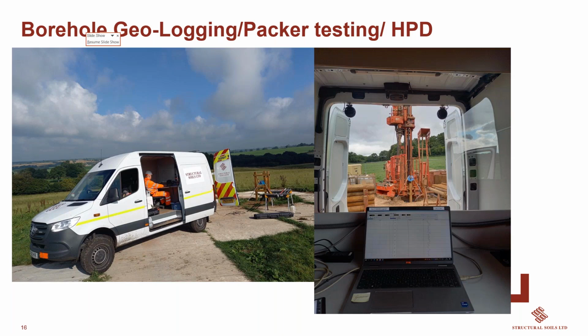So once we've drilled our borehole, we need to make sure we get as much information out of it as possible. So what we'd like to do is run some geologging tools down there. This can be done with the rig being in situ, or if the rig needs to move on and go to another borehole and carry on drilling, we can run it with a tripod and run the tools up and down the borehole without the rig. So we're minimizing the downtime of the rig. However, sometimes with packer testing and with HBD testing, unfortunately, the rig does need to be in situ. So again, we need to basically keep a handle on the program on that so that we understand how things are going.